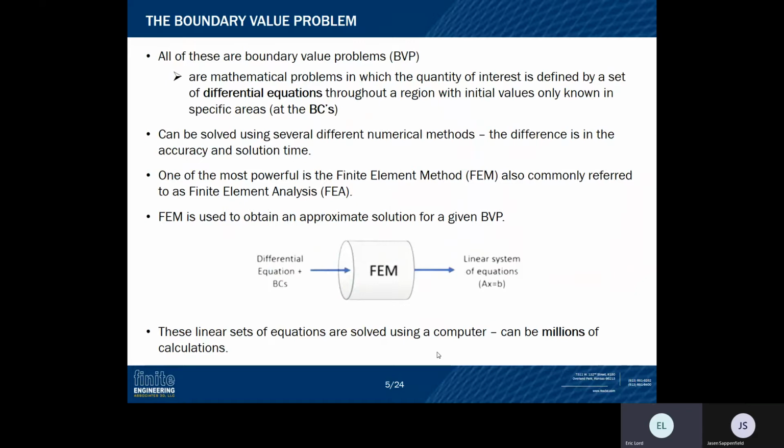The finite element method is used to obtain an approximate solution for a given boundary value problem. We essentially have our differential equations and our boundary conditions, and then we feed that into our finite element method. And what we end up with on the output side is a linear system of equations. These would just be algebraic equations in the end to describe these differential equations. And these linear sets of equations are solved using a computer.